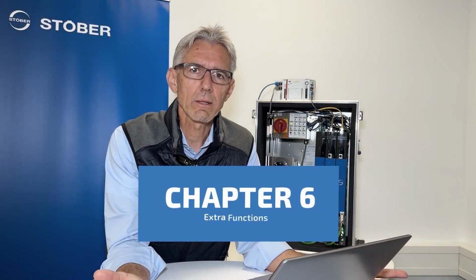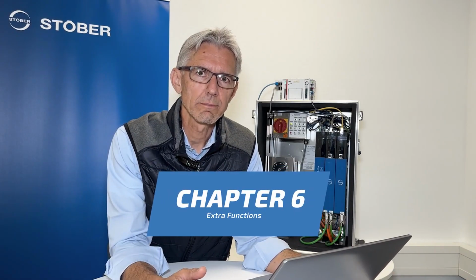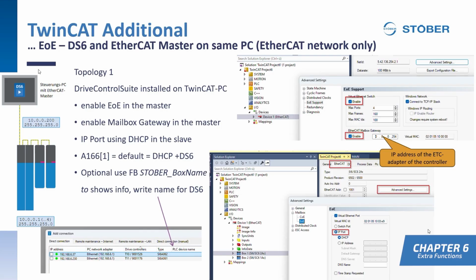Now we are already done with the functions for the machine. Now we can add additional features like EoE so that we can tunnel Drive Control Suite through EtherCAT. There are two topologies. In topology 1, the Drive Control Suite is installed directly on the control PC. EoE is simply activated. On the master, you can activate the mailbox gateway. The slave addresses are assigned via DHCP.